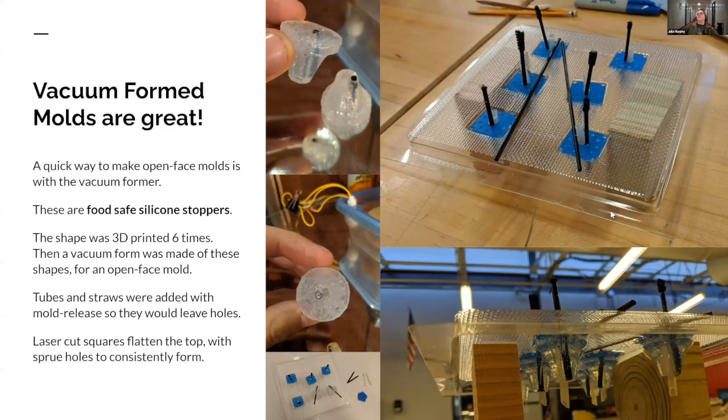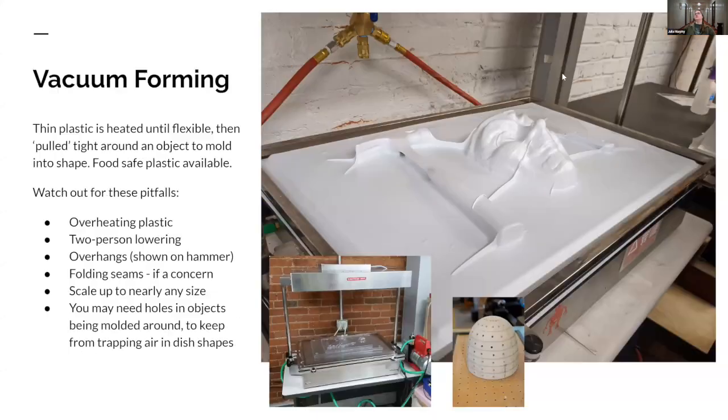So bonus. Vacuum forming is something that we can do that is very fun. And if you're doing a simple candy mold or something like that, you absolutely can use this as a way to make molds. So if that's something that's interesting and you're doing a part that doesn't have any kind of mechanical lock to it, meaning it's not grabbing, so it doesn't have to flex around it, then it's absolutely something that is available to you.